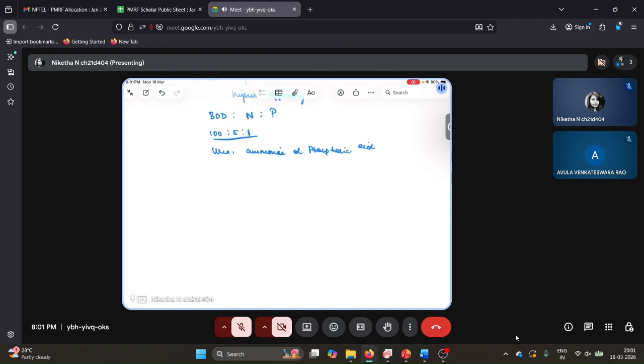Okay, coming to anaerobic processes, like aerated lagoons, we also have anaerobic lagoons. Now this is for combined mill effluents. If we have an integrated mill and we are getting a combined effluent, then we can go for an anaerobic lagoon.